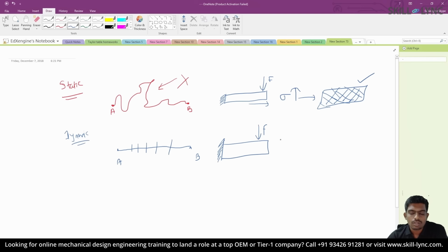Here, if you apply the same load on the cantilever beam and perform a dynamic analysis, you can see how gradually the stress increases, and at each time step, at 1 second, 2 seconds, that is, if you want to look at the stress result at the end of 5 seconds, the results prior to the final step, that is the first second result, will be reliable as well. Hence, the dynamic analysis requires more computational effort than a static analysis. So, depending upon our requirement, we choose whether we want to perform a static analysis or a dynamic analysis. And finally, to put it short, if someone is interested in looking at the deformation at the end of loading, they can just perform a static analysis and look at the final deformation. If you are interested in looking at how the deformation progresses, you can perform a dynamic analysis on it.